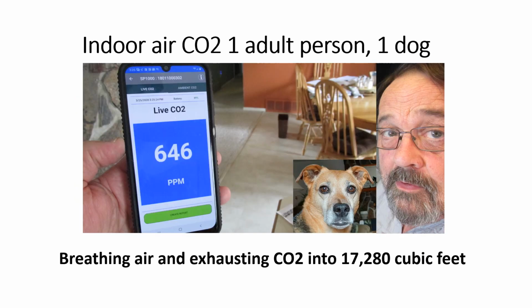So we begin our test, indoor air CO2, one adult person, that's me, and my dog, Sophie. So we're breathing air, oxygen and nitrogen, and some CO2. There it is, we're measuring, that's how much we're breathing in. And we're exhausting CO2 into 17,280 cubic feet of air. I turned the furnace off so that there's no air moving through the building. I've got all the doors and windows closed. Comparing the outside measurement now to my inside air quality.